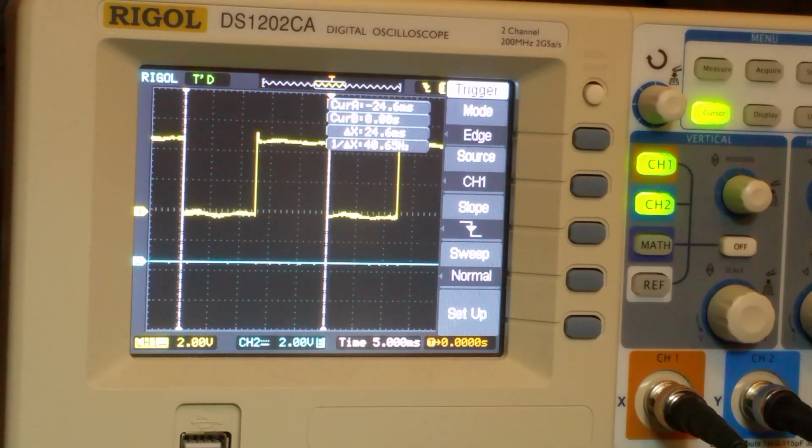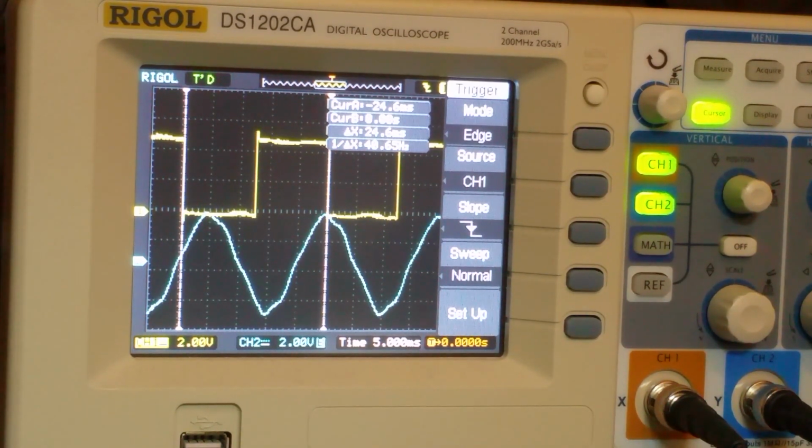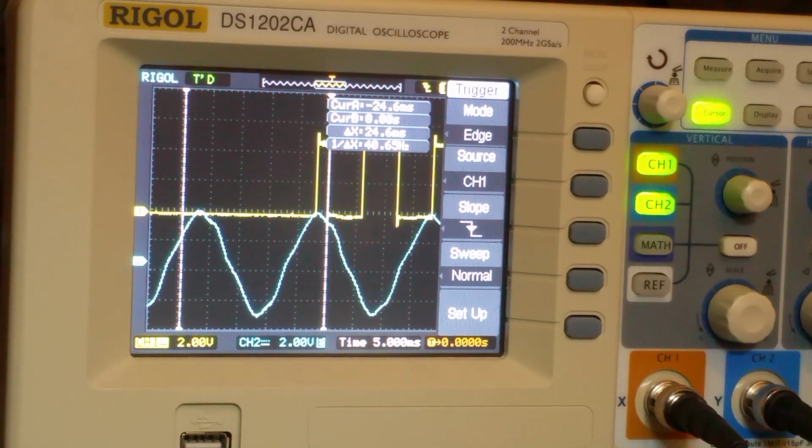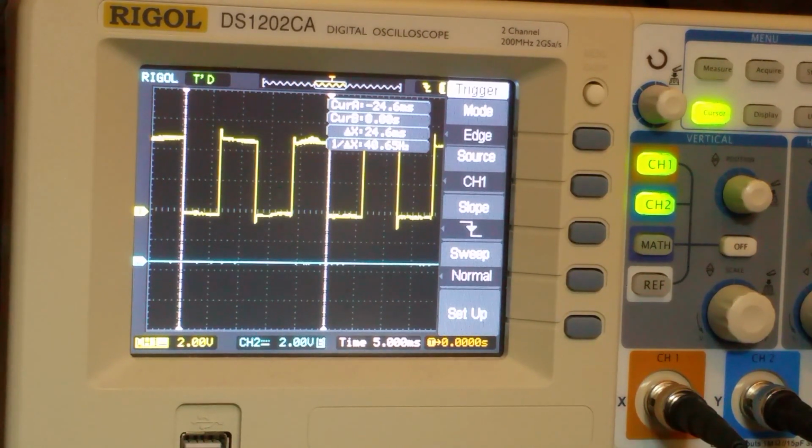So there should be 65,536 cycles, or should there? So we'll have a look. And that's why I'm going to look at A14. What you can see here is, obviously, it has half the cycles because it's just a counter, and A14 has double the frequency of A15.